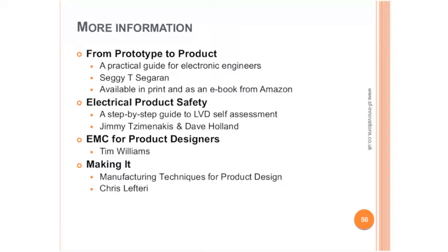The parts which tend to fail are going to be the mechanical parts, really. So you could do life testing on that by rigging up some sort of actuator to operate the buttons, etc., to work out the life of the product. People may be familiar with the bathtub curve. Most products tend to fail in the first few days of operation. If they get past that, they tend to work, and then there's failure when components start to wear down. So what a lot of manufacturers tend to do is to burn in the product.